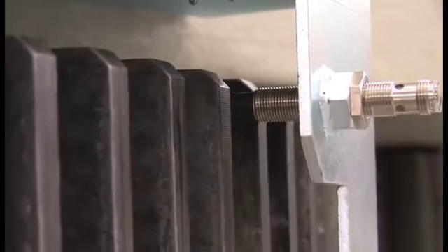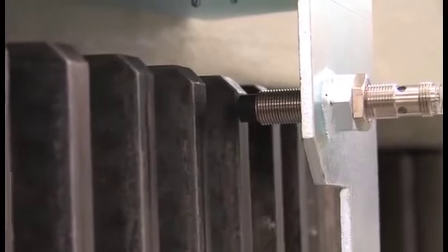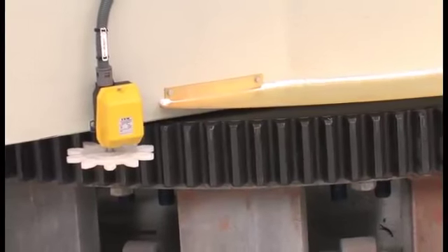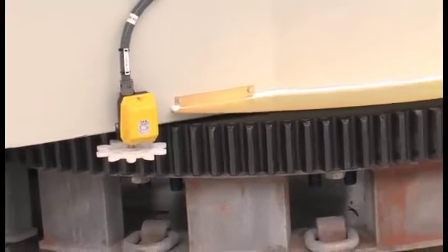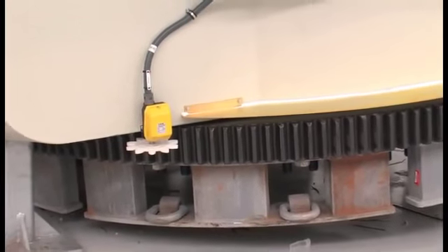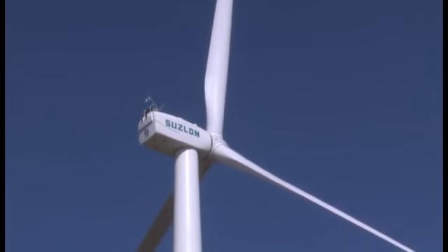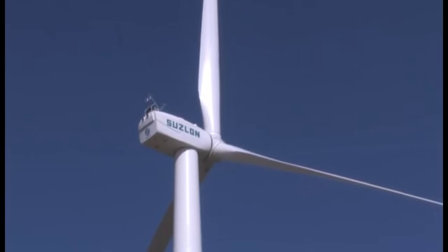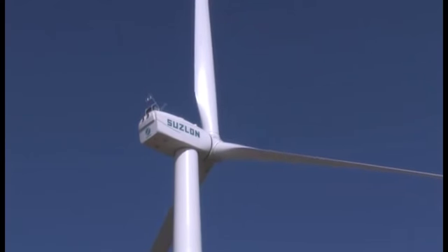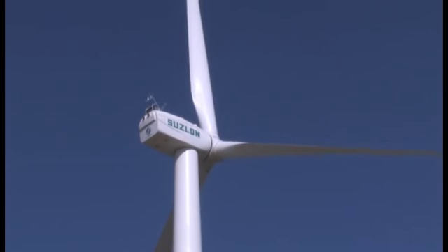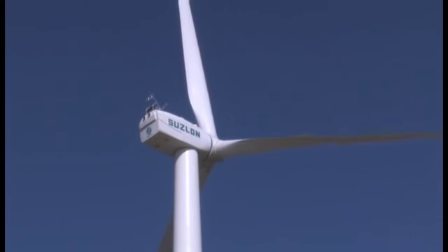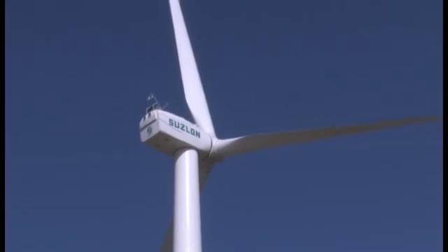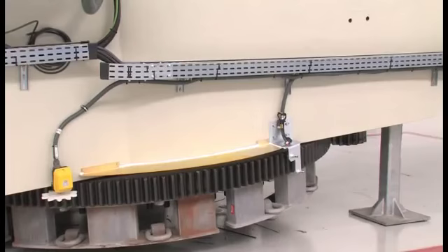Sensors detect nacelle rotation, and the controller counts the revolutions. If the twist becomes excessive, the controller will put the turbine into a stop state and rotate the nacelle to untwist the cables. If the nacelle is pointing 180 degrees away from the wind, the controller will determine which direction will untwist the cables and then turn the nacelle in that direction to realign it with the wind. In the next section, we'll look at the sensors used in a typical yaw control system.